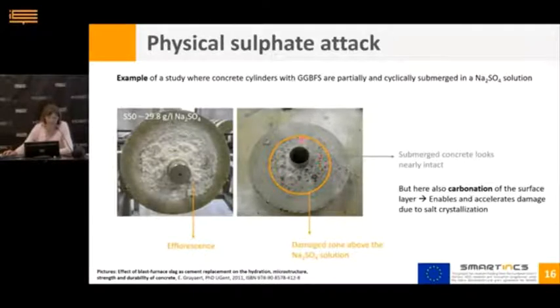And we could have this degradation because these specimens were made out of concrete where the binder consisted 50% of blast furnace slag. And the more slag is in it, the more vulnerable it is to carbonation. So we had superficial carbonation of the outer layer.